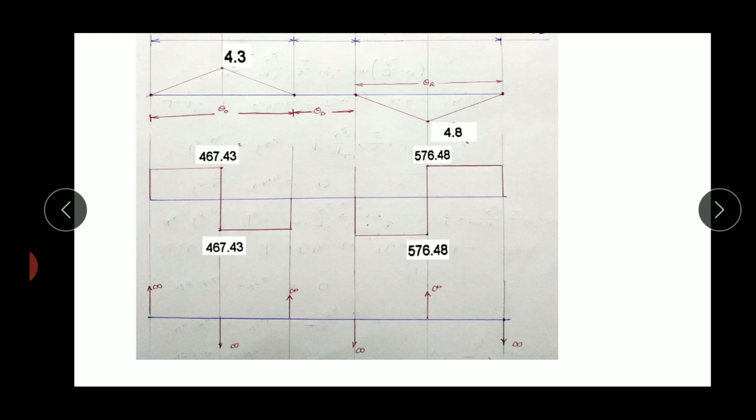As this constant acceleration requires an infinite amount of jerk, at the start of outstroke we have to show infinite jerk over here. Similarly, at the half of outstroke, the acceleration was positive and suddenly it reaches a constant negative value, or retardation value, so it is represented by a vertical line.